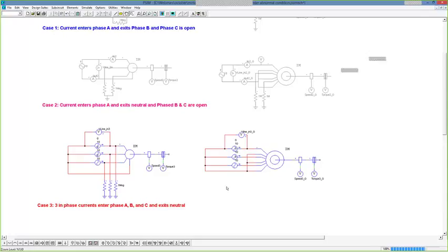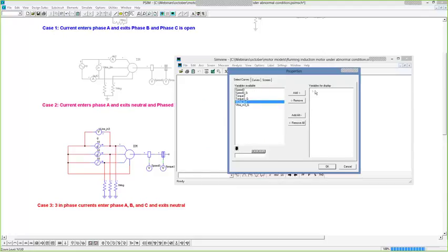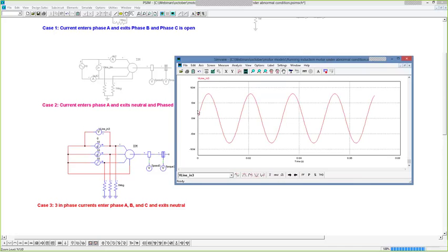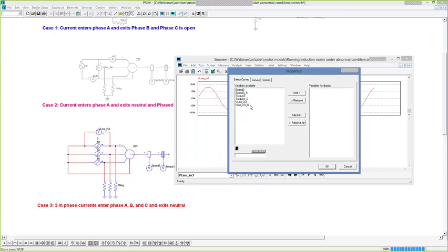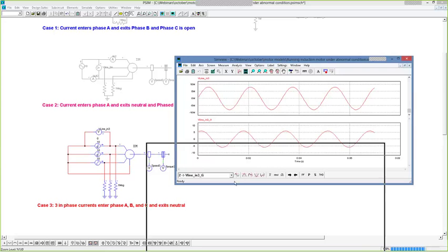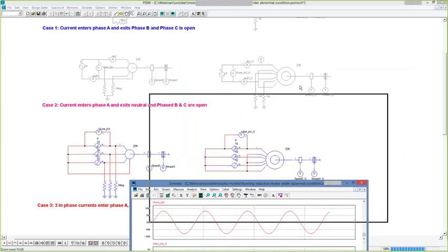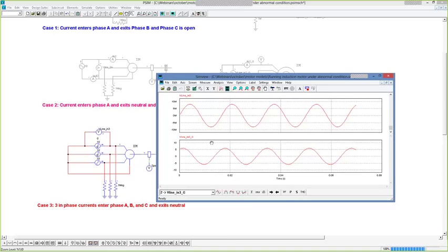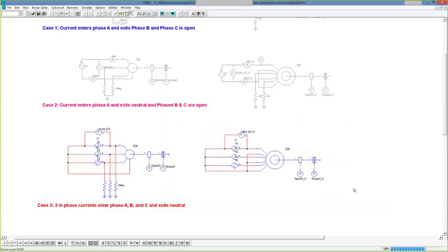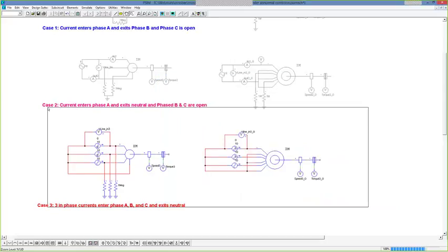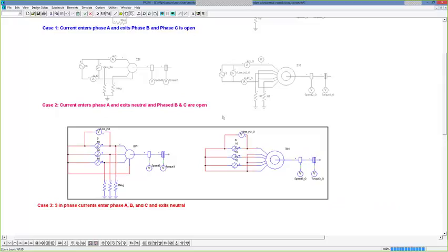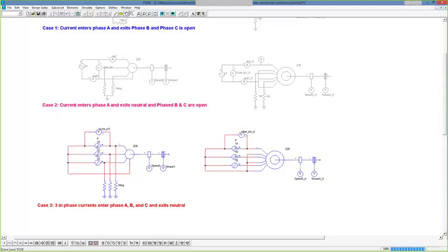They're going to be different, so let's plot them on different scales. We're seeing plus minus 7.5 million volts on the symmetrical model, and on the general model, a more realistic plus minus 5 volts. This is a good example of why you need to decide what sort of simulation you're going to run, and choose the appropriate model from there.